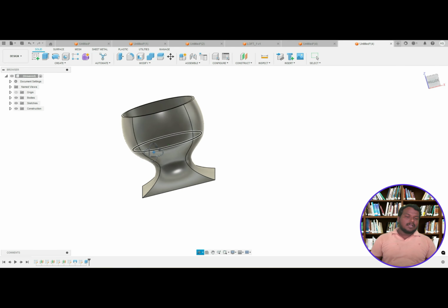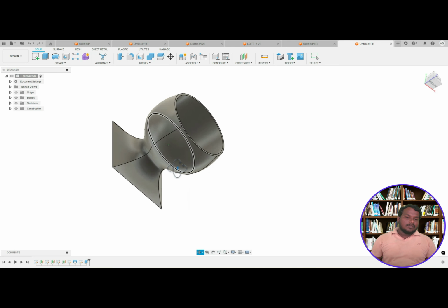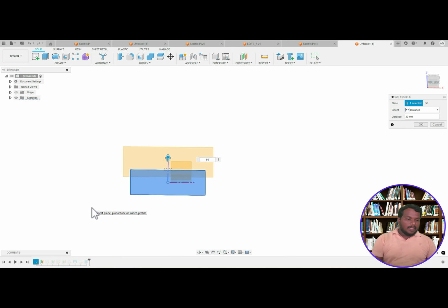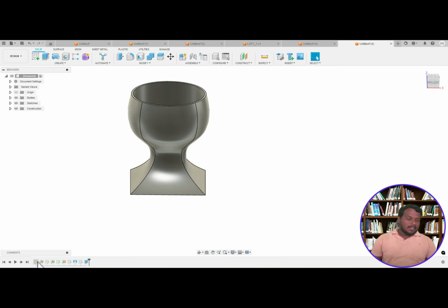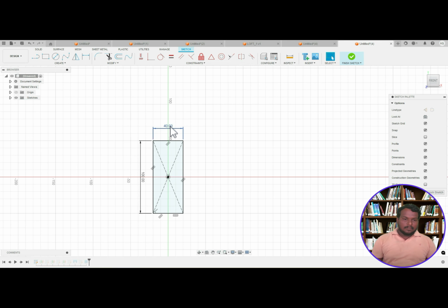You can see the teacup or glass, like that glass only. So for that we make the glass. So this plane, you edit feature, will be around 50 mm. Okay, and this rectangle also make it 40 by 40. Okay, finish sketch.